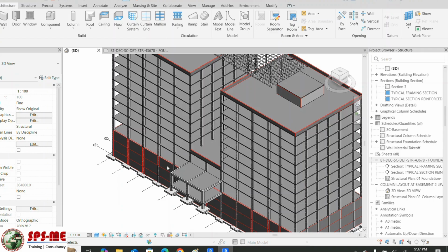And quantity you can do in another way. Suppose you have 100 columns here, that you can take, right? You can take the quantity, and you have given the rebar, and all these 100 columns are typical, and you can count the rebar from one column. Then accordingly they do the calculation. You got what I'm saying? It is typical, okay, but I don't think all are typical. Yes, not all are typical, but whenever there are changes, they have to do it separately.